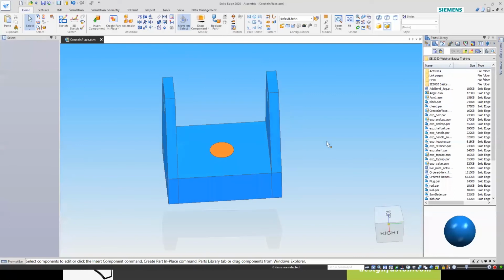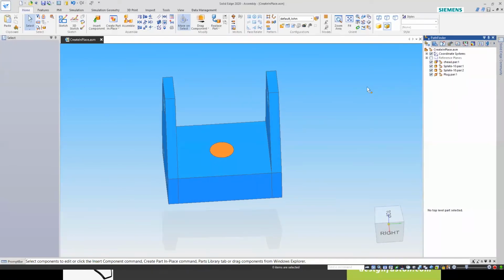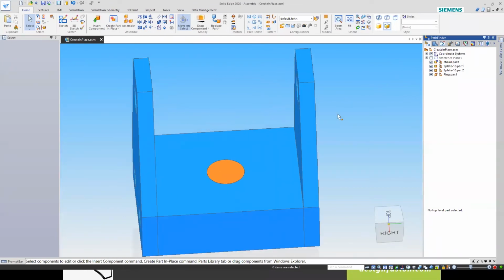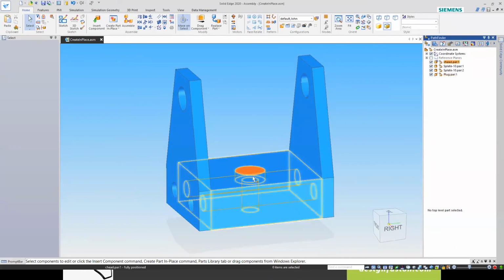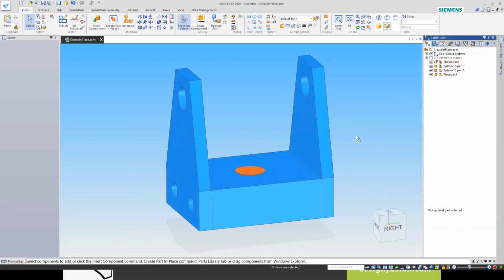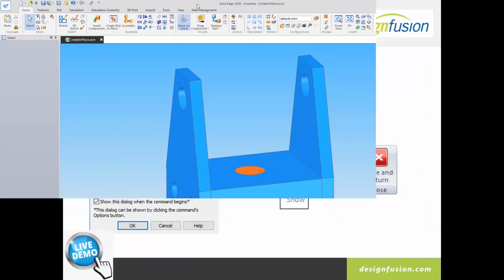Now, keep in mind, and this is important if you're new to assembly work here, that this is linked. Actually, this one isn't because I had the link turned off, but you can create this linked to the inside edges. In other words, if this size adjusts, the hole adjusts, so will the plug. That may be good, unless you're using this plug in another part, and we teach you how to deal with that situation in the fundamental course. So we now have this plug fully created and positioned there. So let's go back to the PowerPoint.